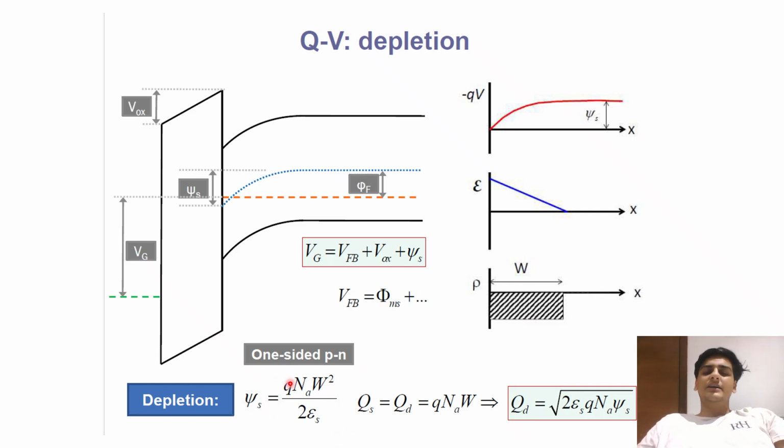And we use the diode formula that we derived in the last class for this, because we essentially approximate this P as being part of a one-sided PN junction where the other end is so extremely doped it's as if it didn't exist.